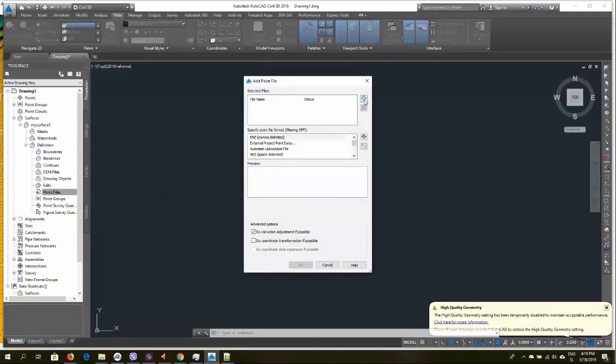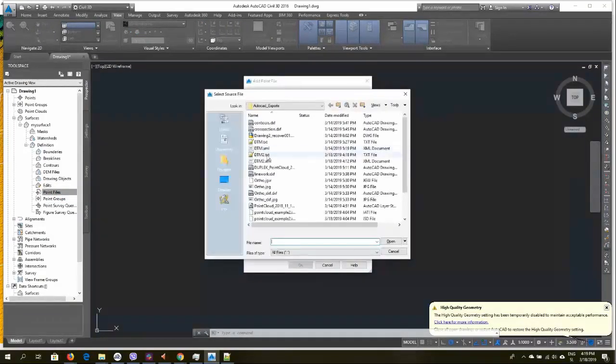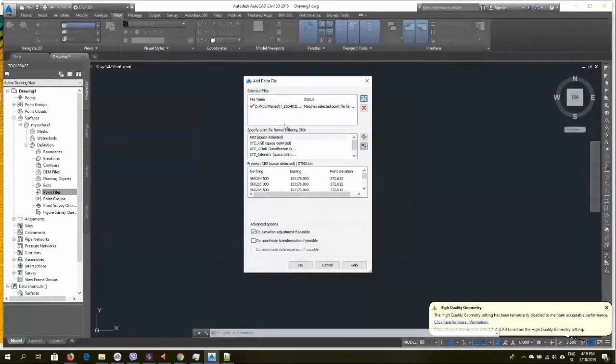Now let's go to our DTM2.txt file, double click on that one. Now here just be careful, so if you are importing a surface from a 3D survey, probably you will be using easting, northing, Z. So X, Y, Z or easting, northing, elevation.